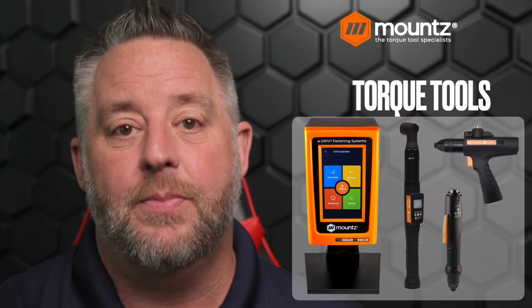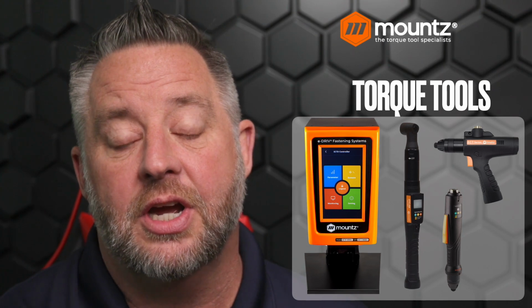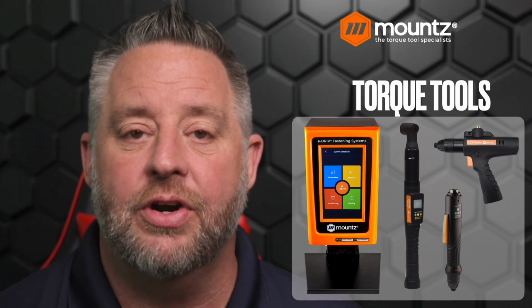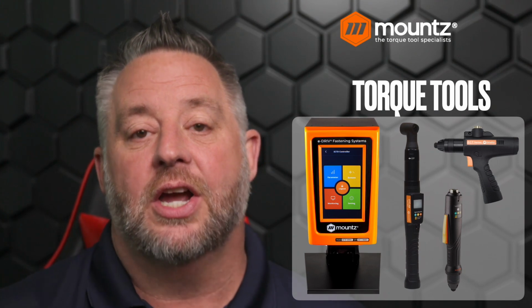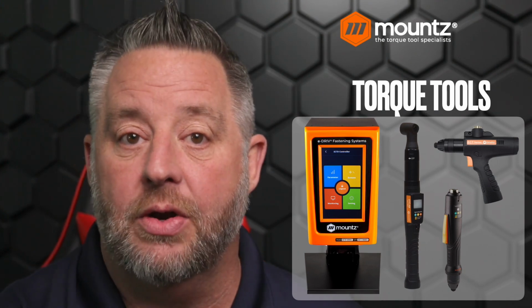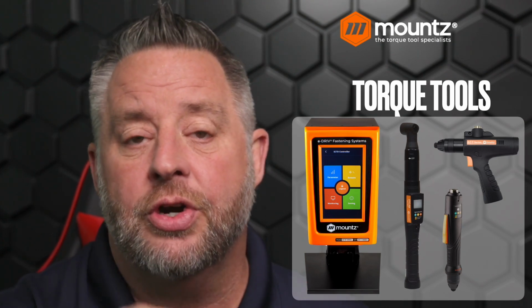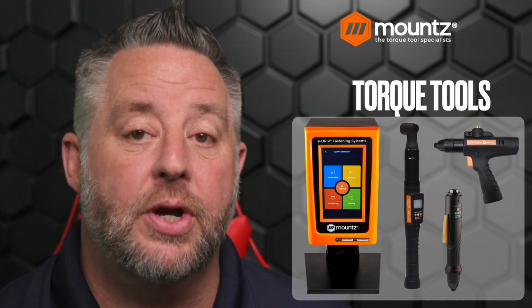Next step up from the electric tools are going to be DC electric control tools. Now, these tools act very similar to the electric tools. However, they aren't controlled by a spring clutch. They're actually controlled either with a torque sensor that we talked about, the strain gauge when we measure the torque, or they're measured by current. So the amount of current draw is coordinated to the actual torque output.